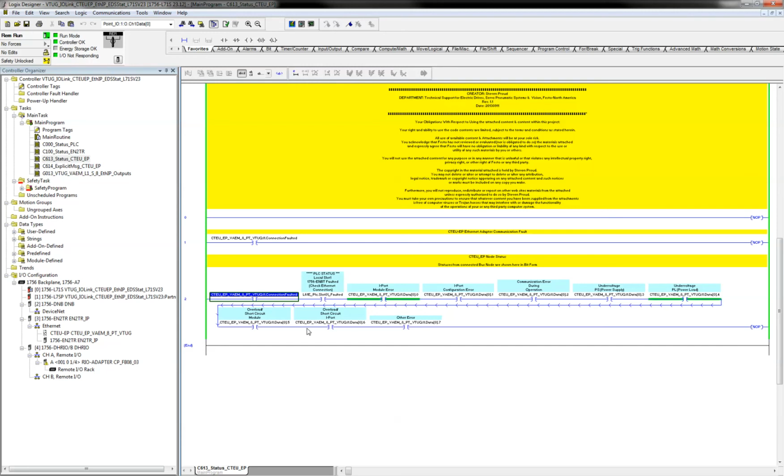And what I'll do here is I just drop the load power. So the load power, it tells me that I have an I/O module error. So it's reporting that this module in general has an error, and then the load power is an undervoltage right now, meaning you dropped an e-stop or something. Turn that back on.